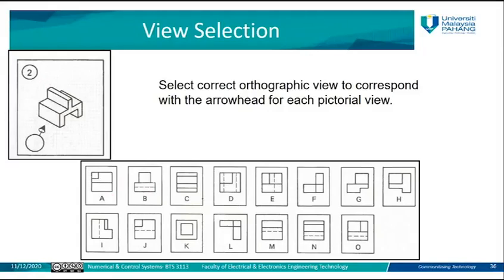Which of this figure is it, A, B, C, which view here reflects the top view of this figure, for example. So it represents the figure M, because we have one rectangular and another rectangular here, and also another rectangular. So for M, the middle one is not complete because on the down here is not a solid part, so it will be represented by this dash. On the other side, you have one rectangular here and another rectangular, but because it's not solid material, it's represented by such dash points.